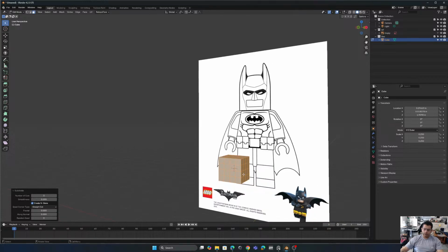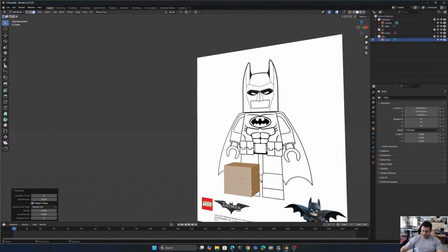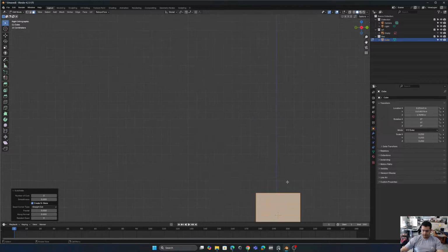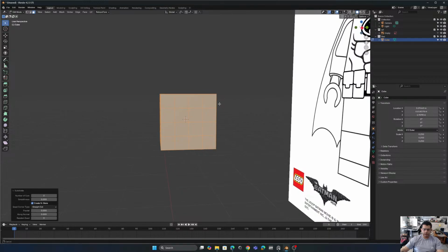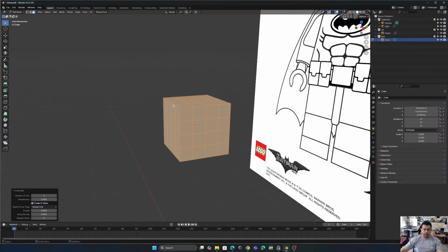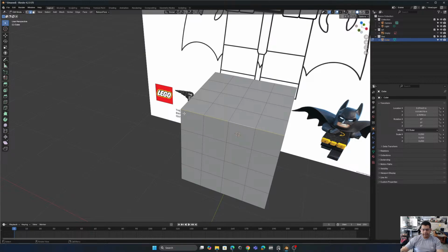Right now what we're going to do is create here. We're going to go to the right side, move a little bit with Shift and scroll. We're going to try to center in our view, and we're going to press 2 to select edges, and we could press Alt to select the whole loop. As you can see, if I press Alt and click over one edge, I could select all the edges that are connected in one line.